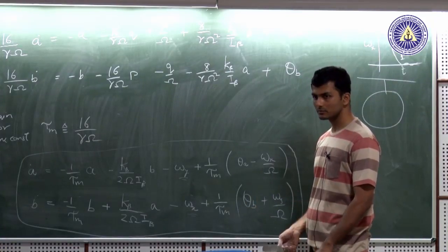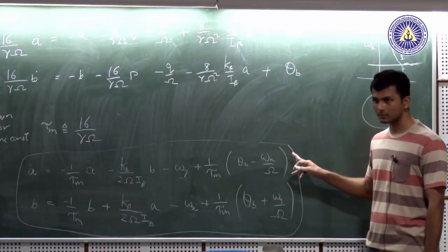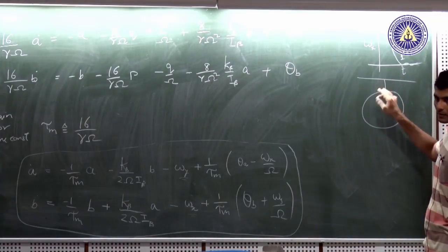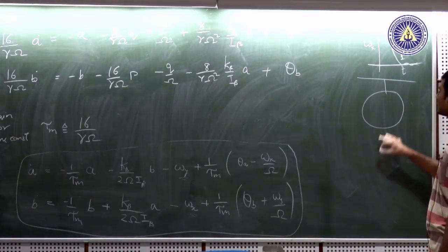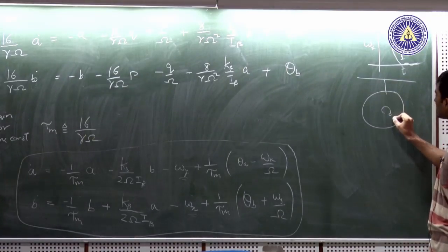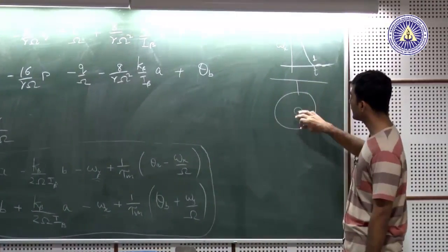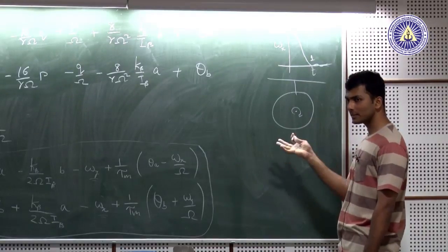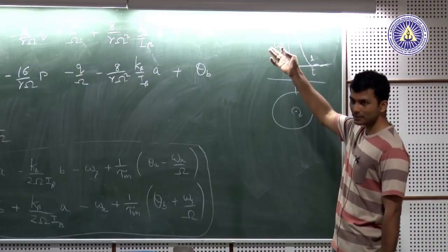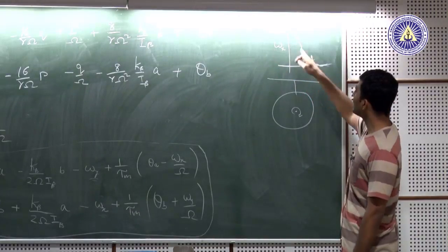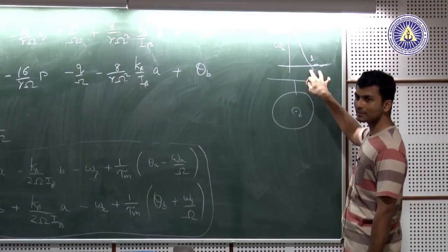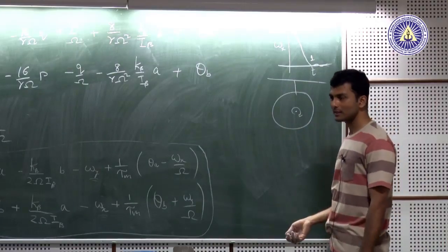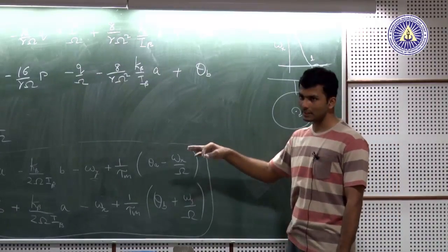Which point? The removal of the cross coupling, the damping. I'll show you the plot because this is just a rough drawing. No, what did you start with and what happened next? So if you give a large angular velocity, this is my helicopter and this is my body frame x-axis. I'll come and externally give it a large angular velocity, let's say like 360 degrees per second at t equal to 0. It will damp down to 0 in less than a second, almost a second's time, for the small scale helicopters that we see. So that indicates the presence of large damping in the system.